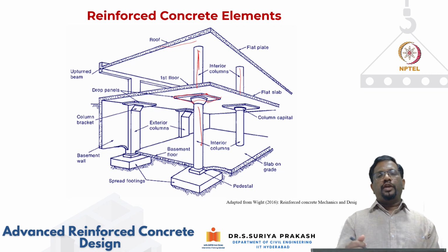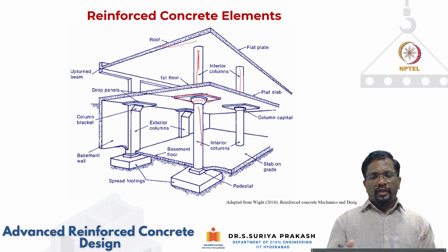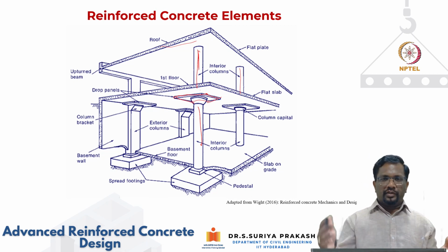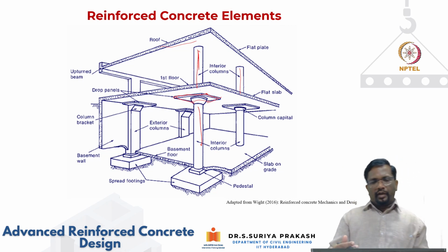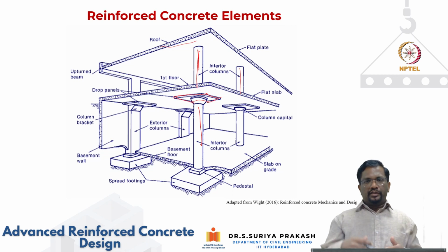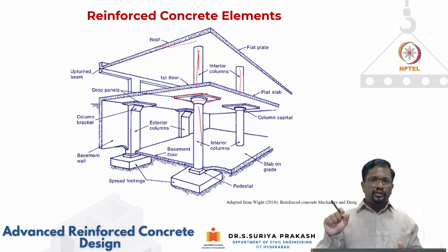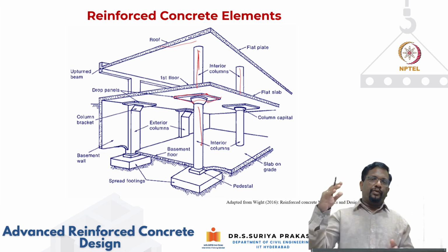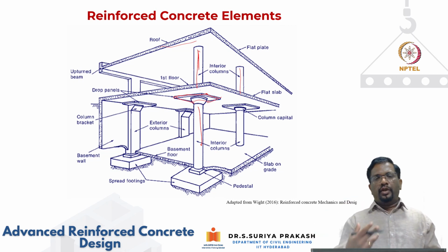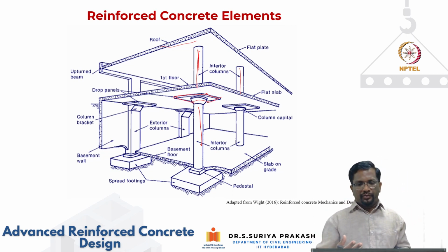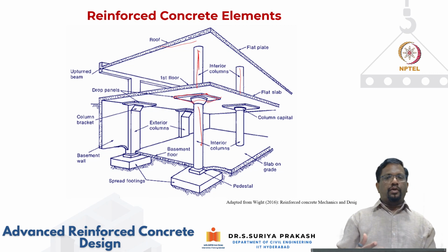But the advantage with this kind of system is, you get rid of the beams. So aesthetically, it looks very pleasing. And for example, if you have height restrictions in terms of total building height, then if you are able to remove these beams at each floor level, then in fact for the particular height you can construct additional floors. So from the owner or client point of view, it is going to give you a lot of advantages.